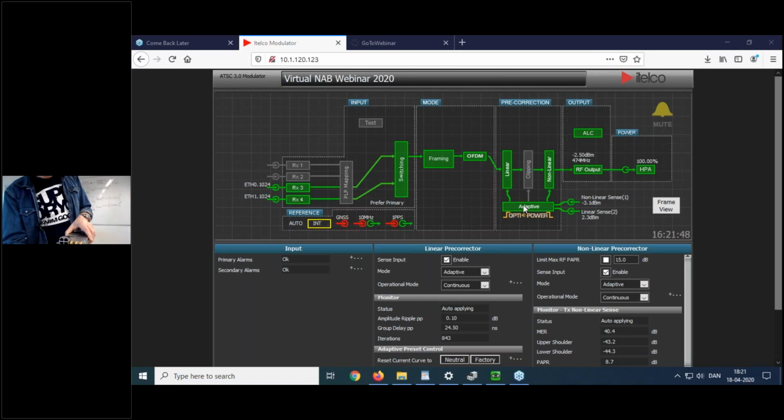We have the RF output, and then we have 2 sense inputs for feedback, respectively after the amplifier and the output channel filter for the precorrection. I will come back to that. Then there is actually a connector here with a lot of programmable pins, so we can control and monitor many things. There's for the GPS antenna and some ASI and SMA connectors. There's an expansion slot here for our internal processing machine, so that we can add future things. And I promise you there will be exciting things coming out from here.